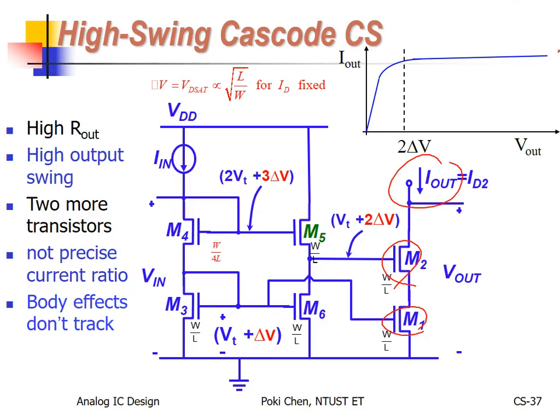In theory, for transistors to operate in saturation, they need to operate in saturation usually, to realize any kind of function. Usually. For some very special cases, we would like them to operate maybe in triode region or even in weak inversion. But usually, those transistors need to operate in saturation region.